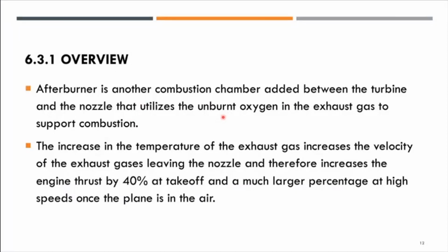in the exhaust gas. Basically, what will happen is that the high energy flow of gases generated from the combustion chamber still has high energy when it comes to the turbine stages. Right after the turbine stage, we introduce another set of combustion where fuel is injected to the area.